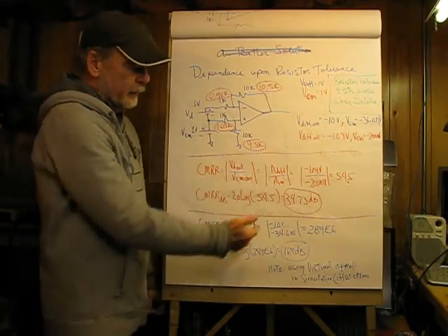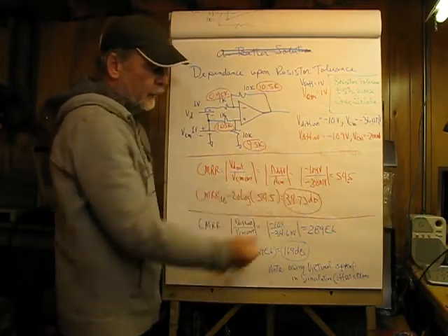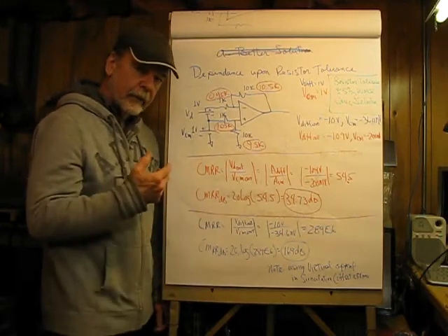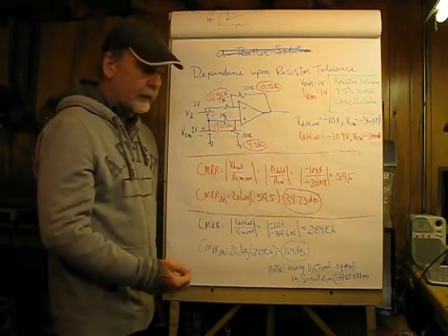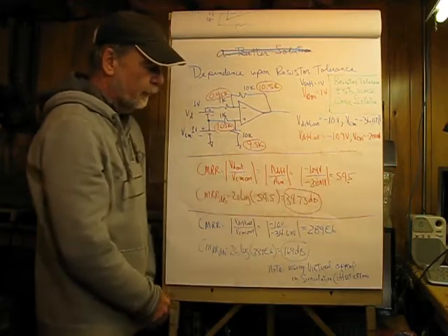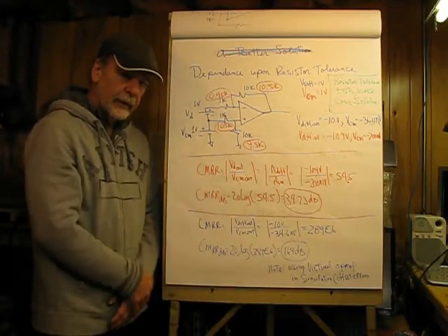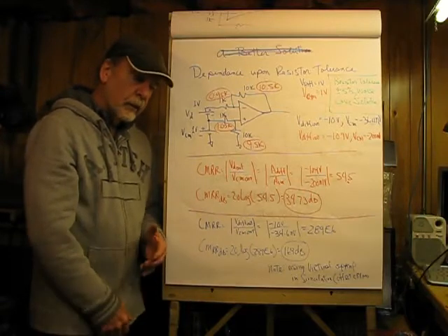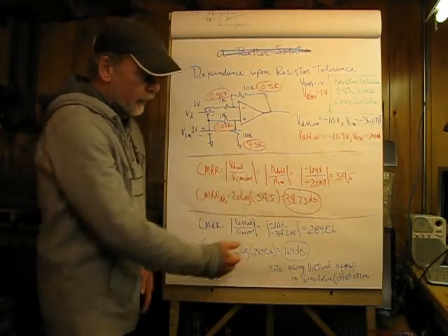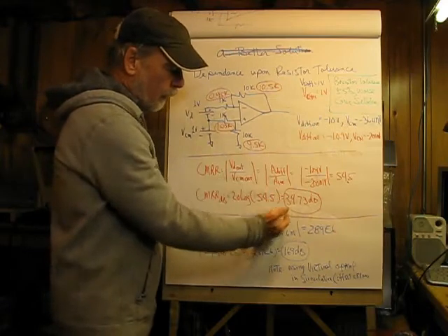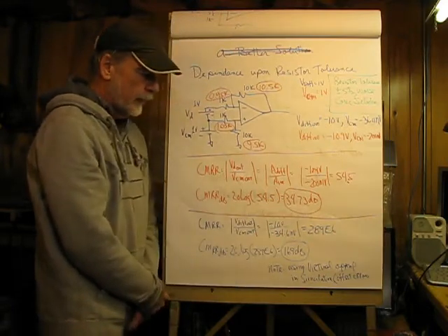So if I take my negative 10.9 and divide it by 200 millivolts, what I get for the ratio in the linear domain is 54.5, and then converting that into log domain, which is typically the way common mode rejection ratio is defined, it comes out to be a horrible 34.73 dB.